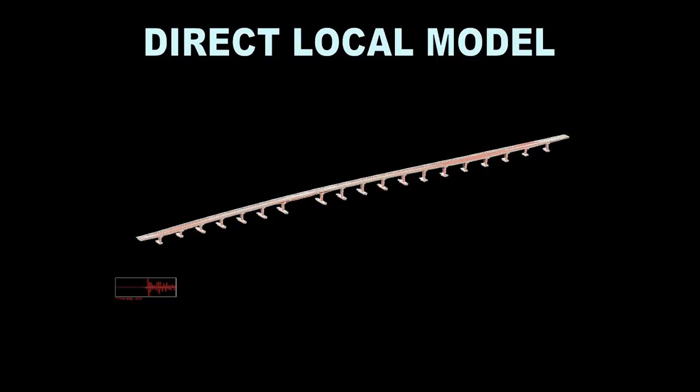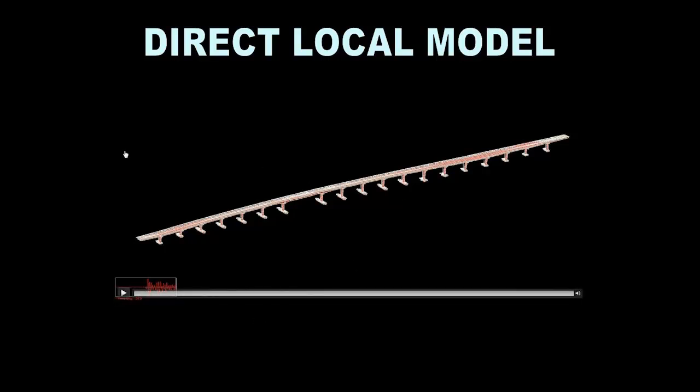In this substructure model, I have decided to keep the pile cap because it's very massive, and put the mass of the piles in my 6x6 mass matrix. But I kept the pile cap because it's very massive.